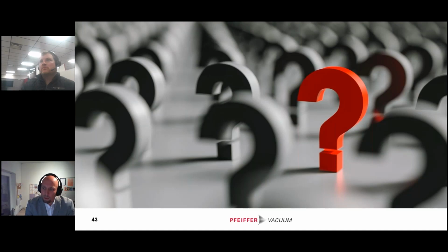So one interesting question we have received, Nick. From your opinion, is there already somewhere a standard which tells you which test procedure to use? Are there standards you know from, or are there some under way? SAE is in the process of a couple different studies and standards, or the creation of a few standards, to kind of delineate that right now. Right now, you have to look at what leak rate you're looking for, or what size defect and what leak rate you're trying to detect, and then you have to pick a test method based off of that.